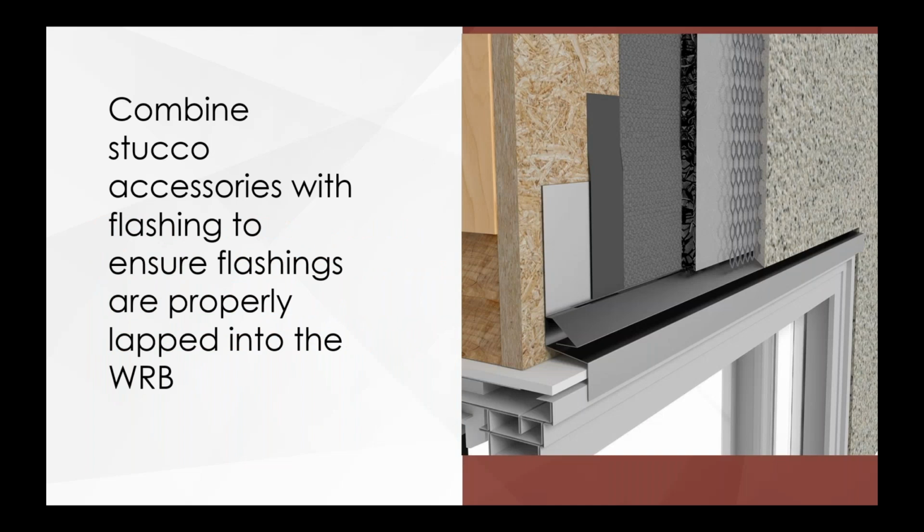There's a lot of different ways you could do this. So I've got a few designs up here. Again, what we've got is a window head flashing out here. And then we've got a weep screen. That could be done with 2 pieces. It could be done with 1 piece. But one key thing to this is if you're using a drainage mat here, you want to make sure that drainage mat is going to feed into an exit.